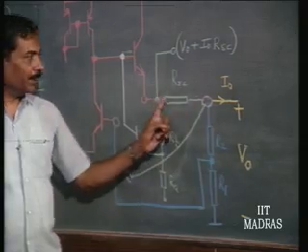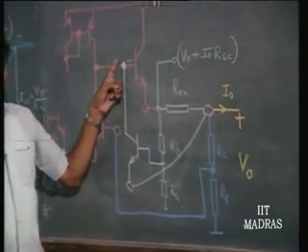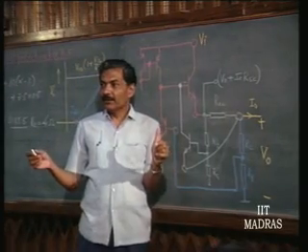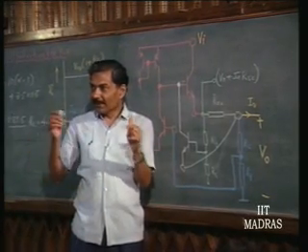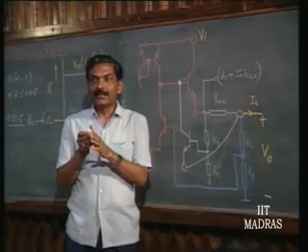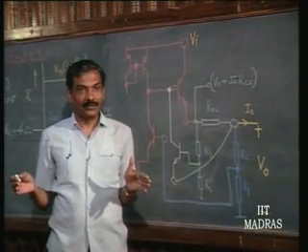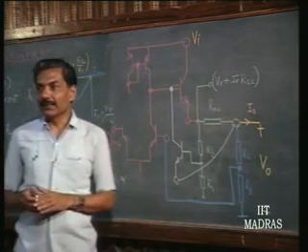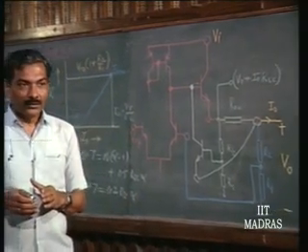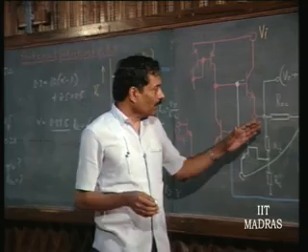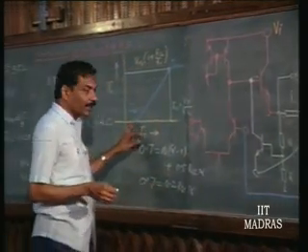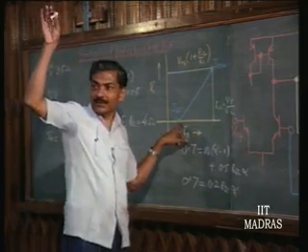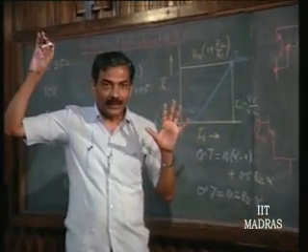So, 2 volts drop here and then 0.7 and then 0.7. That means the Vi minus V naught requirement, that differential requirement, is increasing. This is how things are going to result. If you therefore try to go for smaller and smaller hold current, which is going to be only an eventuality when a short circuit occurs, which is also supposed to be quite a rare phenomenon, right.